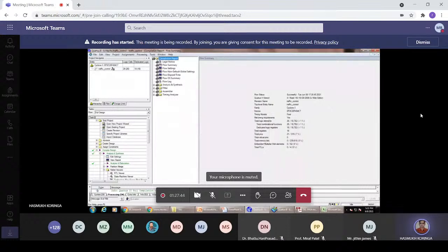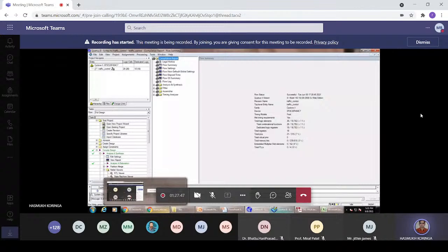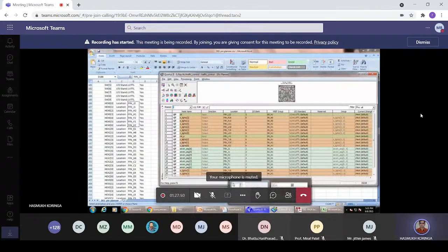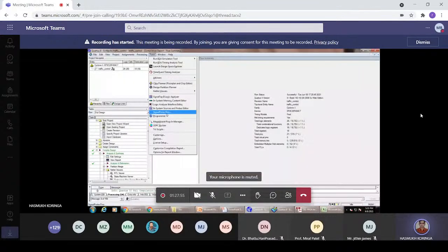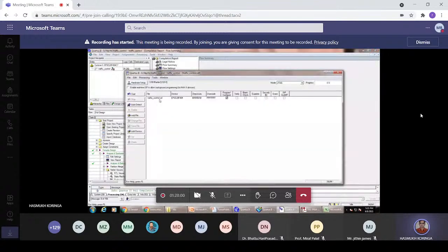Next step is, after the full compilation, go to Tools, then the Programmer. Once you click on the programmer, the current project file you have compiled appears, and its programming file is the .sof. As I told, the Cyclone II is an FPGA chip, so its programming file is the .sof, the SRAM object file. It will set the hardware to USB Blaster. We program through the USB Blaster and click Start. It will start programming the FPGA board.